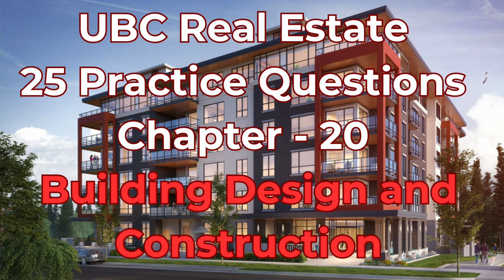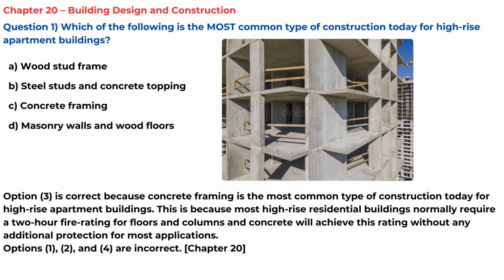Ready? Let's dive in. Question 1. Which of the following is the most common type of construction today for high-rise apartment buildings? Option 3 is correct because concrete framing is the most common type of construction today for high-rise apartment buildings. This is because most high-rise residential buildings normally require a 2-hour fire rating for floors and columns, and concrete will achieve this rating without any additional protection for most applications. Options 2 and 4 are incorrect.